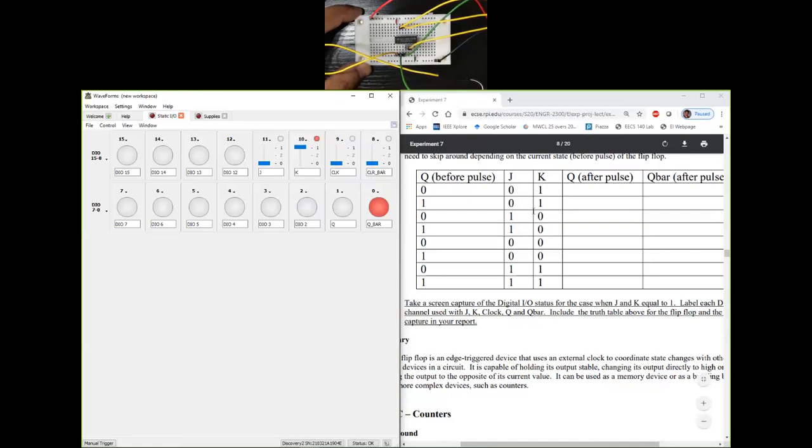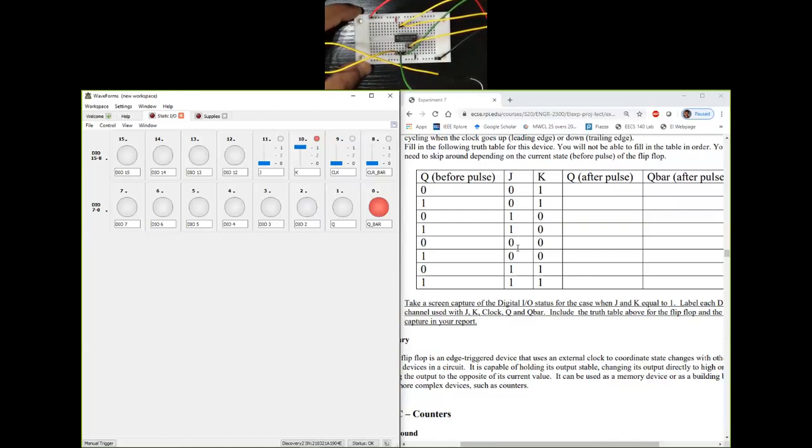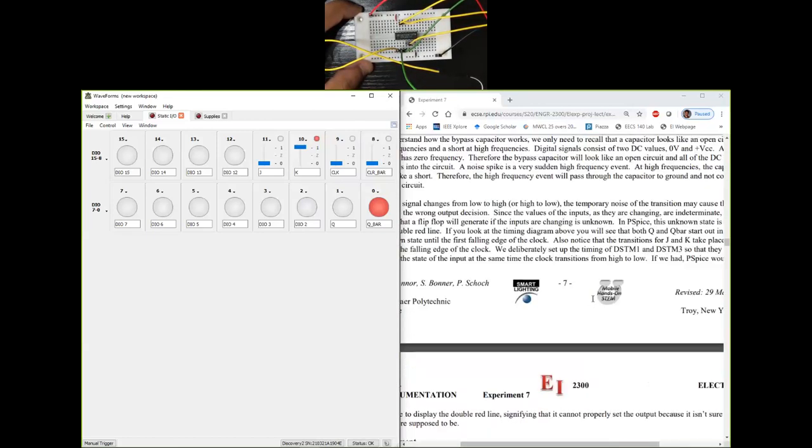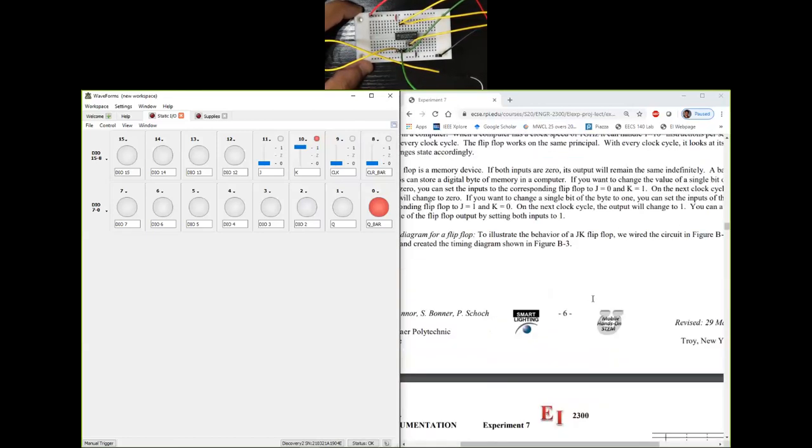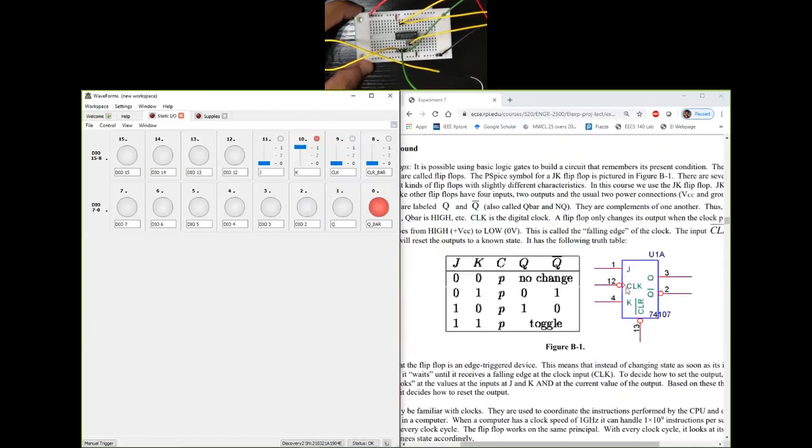One thing that we missed over here was the conversation about clear. And we got lucky because we were in the reset state to begin with. But we can't ignore that anymore. So you see this, there is a clear input, pin number 13. We have connected clear bar to 0, which means if an input is active low, and you connect it to low, that means it is active.